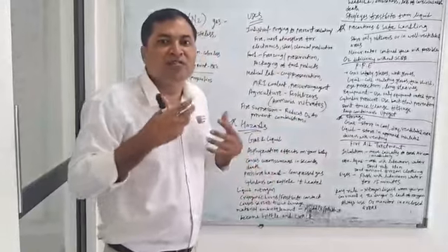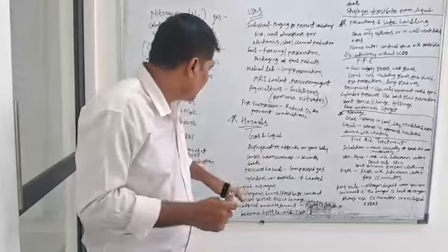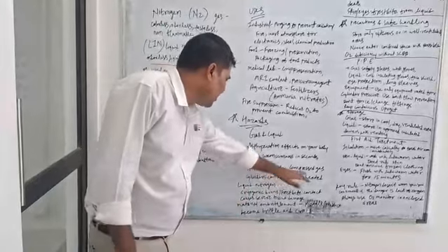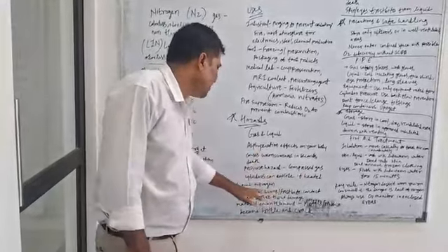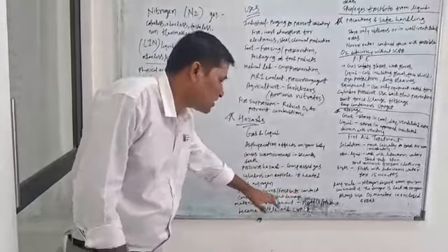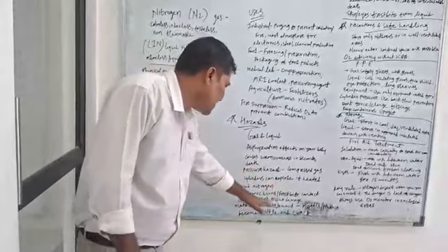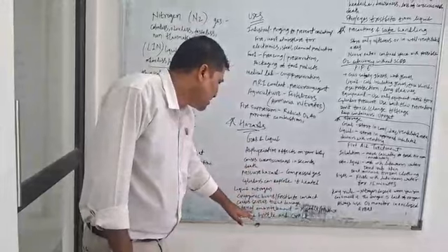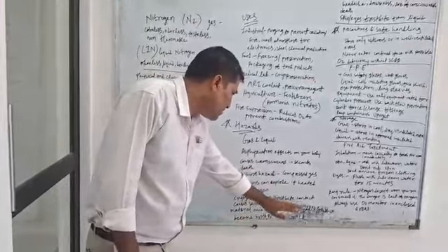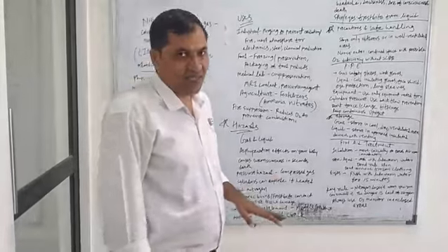So how will you feel? You will feel unconsciousness. Now, pressure hazards: compressed gas cylinders can explode if heated. With liquid nitrogen, there are cryogenic burns. You will get frostbite on your body, and contact causes severe tissue damage. Materials also suffer embrittlement: metals and plastics become brittle and crack.